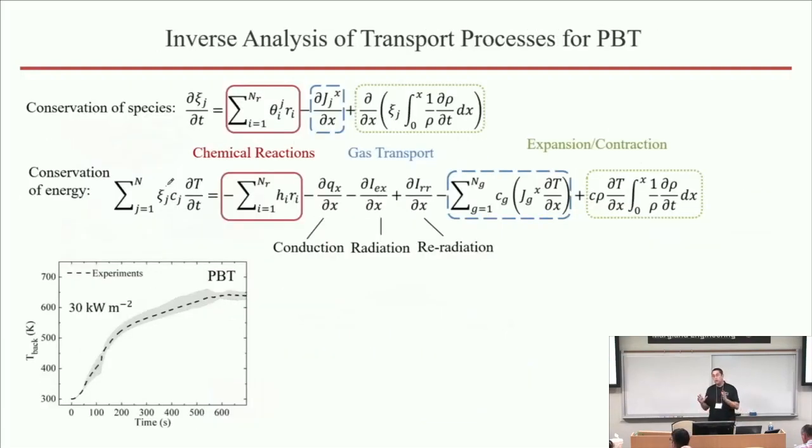And the only unknown quantity now in this test is that conduction term right here, associated with heat transport into the sample, right? What we have, of course, is the back surface temperature of the materials with all defined boundary conditions. So we don't have conductivities, but we have everything else: heats of reaction, reaction rates, and all of that is already parameterized. So it allows us, in a fairly straightforward fashion, to determine the thermal conductivities that give us a correct prediction of this temperature profile. That is done through a set of straightforward iterations.